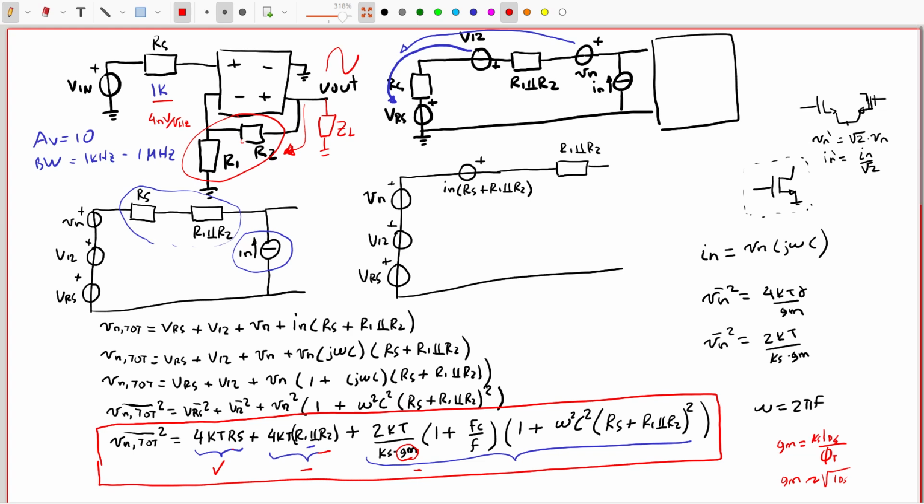Okay, so depending on the application, we will require very good noise performance. Since we don't have a specification here, we will just make some assumptions, and for today the assumption will be that we are going to let the feedback and the input referred noise of the amplifier add around 50% of the noise.